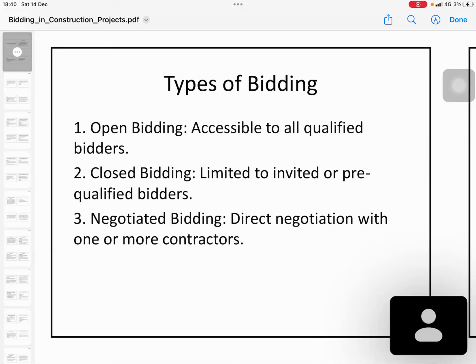All the qualified bidders come forward, all the bid documents are opened and the prices are announced. Again, it is not about the lowest one alone: especially if you are less than the engineer's estimate, most of the time you are disqualified, but the lowest price with all the required specifications and submissions will win. In open bidding, the price is exposed to all relevant parties.